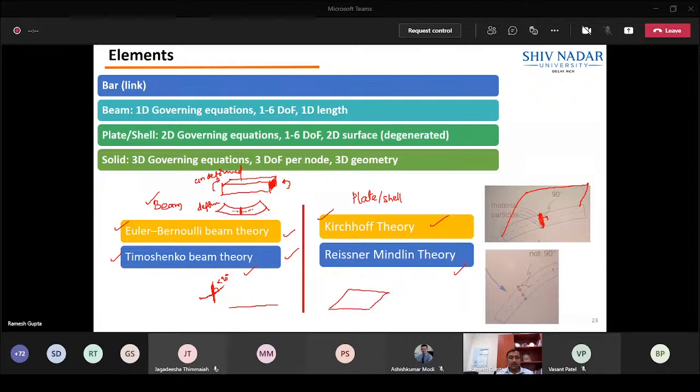Now, the degree of freedom at each node varies from 1 to 6 degrees of freedom. What do you mean by this? Since some of you have already done a hands-on session with finite element, you may already know that when I am modeling the beam, if it is within the plane, then you have x displacement u, y displacement v, and a rotation about the z axis, which is out of the board, which is theta z. So these are the 3 degrees of freedom I can think of.